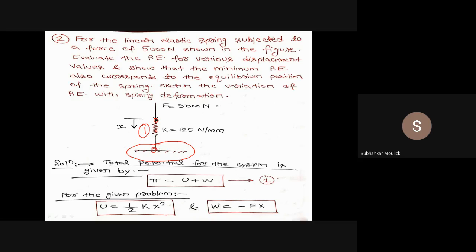So that's why, see, if you apply either a compressive load or a tensile load, the spring will elongate or compress. But since this is a fixed point, this is a wall. In this wall or in this fixed point, will you find some displacement? You will not find the displacement. Displacement is always zero. Now is it clear? Yes, sir. Okay. So that's why at this node there will be no displacement. Only displacement will be at this node. And if I divide this particular element into 100 nodes, that means this is first, second node, third, fourth, fifth, sixth, seventh, eighth, ninth, 10th, all these nodal points will be having displacement except the 100th nodal point.